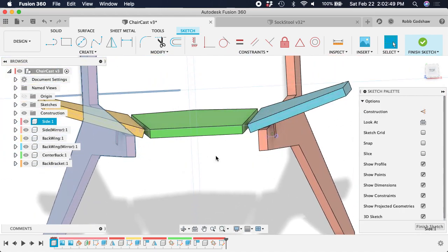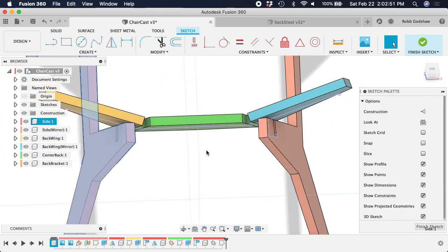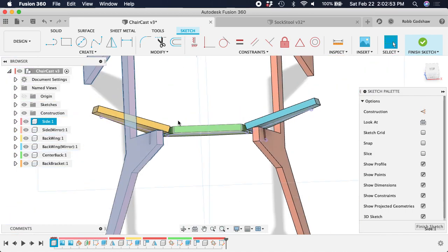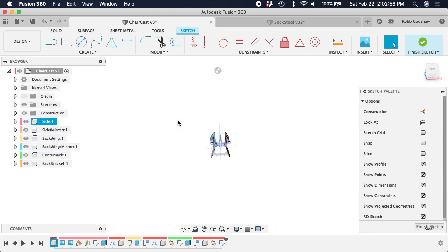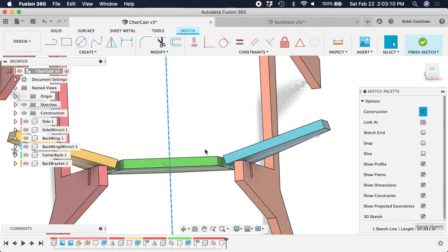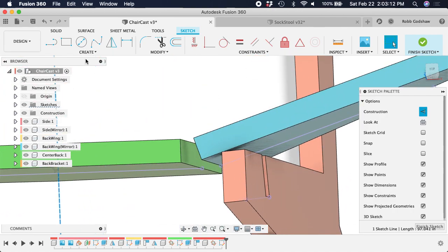Cool. Okay. Now, again, I'm going to drag that line from the top. The reason I have to zoom out for this is because for whatever reason the origin of the sketch is way up here, and you want it to be exactly in the middle. I'm going to join these two things.